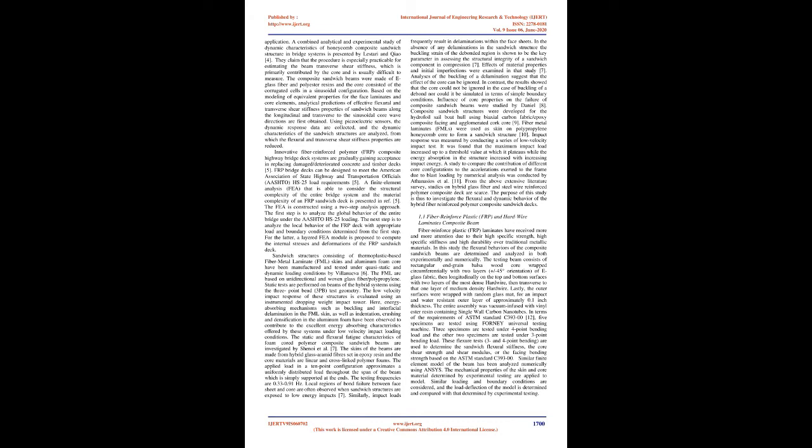A study about innovative alternative systems for FRP bridge decks and trucking industry was conducted by Hassan et al. 3-dimensional, 3D, fibers are used to connect the top and bottom GFRP layers using either weaving or injection technology. Addition of the through-thickness fibers increases the out-of-plane properties of the panel, delays delamination type failures, allows low-cost manufacturing and ensures full utilization of the panel strength. The study describes the fabrication process of 3D FRP panels using the weaving technology.